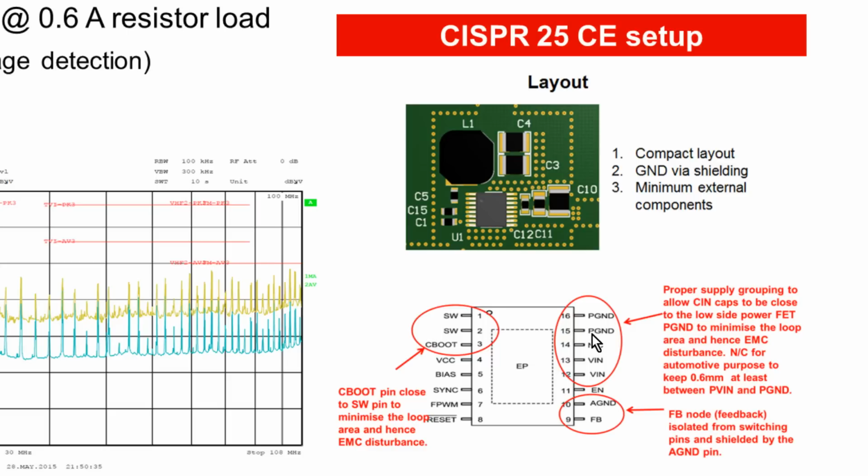Basically you can place the high frequency bypass capacitor, which will minimize the critical input loop and thereby reduce the EMI. So remember, you have a discontinuous input current in the buck converter, which will result in input voltage ripple and will generate EMI.